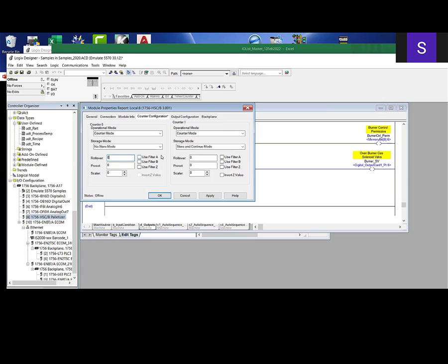That's where the 4 events come from. I have 1 rising A, 1 rising B, 1 falling A, and 1 falling B. And that's the X4 mode I was talking about. So encoder X4, I would get 1 pulse on the rising A, 1 pulse on the rising B, 1 pulse on the falling A, etc. Period rate, frequency, you'll have to look up what all those are, but basically you can tell the difference. This is more of how fast something is moving. This is a count. Counter mode is a lot of times what I use.